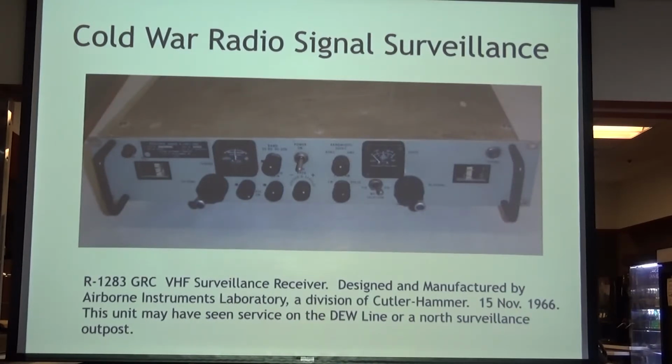They've got a lot of views to get through. I'd like to talk about each one of these things, but there are some things you look at when you find a surveillance receiver like this. There's no squelch control on it. It's not a communications receiver. It has a carrier-operated relay with lots of outputs for various things: starting and stopping recorders, sending tone messages to SAC, things like that.